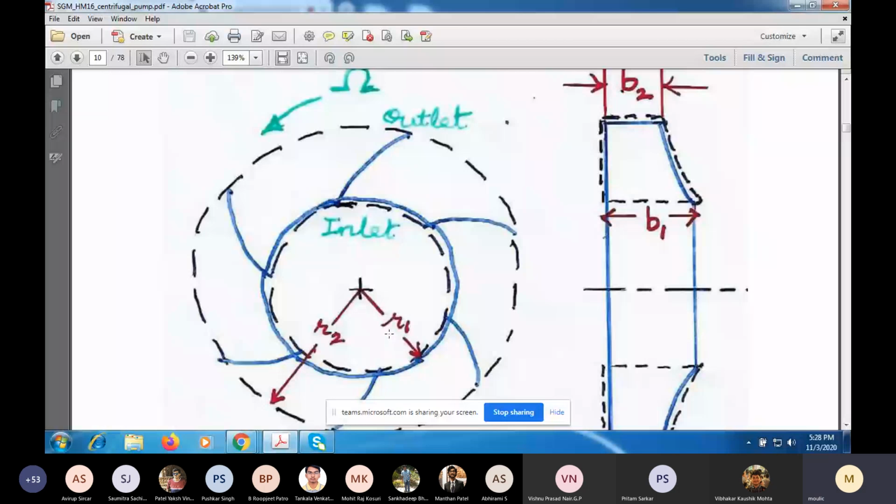But that mechanism is through the no slip condition. So when the rotor is rotating, the fluid particle which is adjacent to this surface here at r equal to r1 will be dragged along by the solid, and it will send the next layer of fluid into motion and so on. But if it's inviscid, the no slip condition doesn't apply.